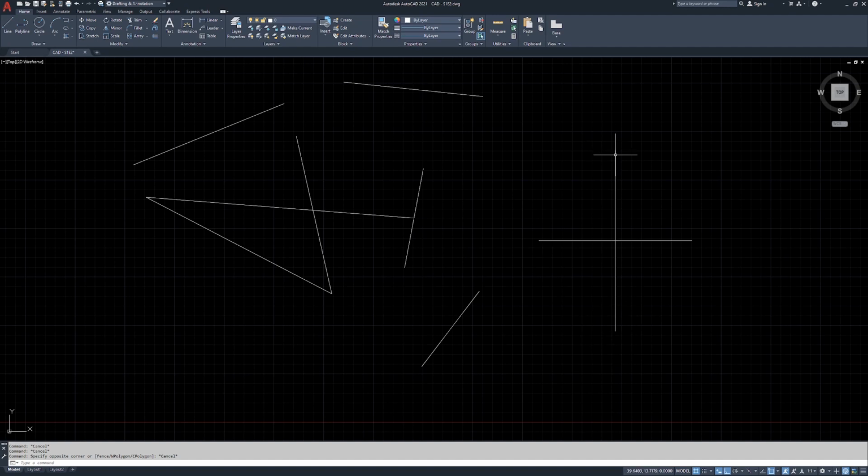So a compass north is typically 0, you would assume. North is how a compass works because it's pointing at the North Pole, but not in AutoCAD. In AutoCAD, the 0 degree is at the east point of the compass. So when we rotated that 25 degrees, it actually rotated it up this way, counterclockwise 25 degrees.